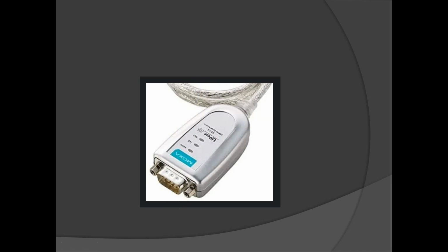terminal like Teraterm, or in the HDK you can open a console and you can frame a message. Okay, you can type a message, any words you can type. So internally, that message will be converted into UART frame format, and it will be given through these pins. Okay, there will be TX pin, RX pin, TX plus, TX minus, RX plus, RX minus. So what you can do is, you can connect the TX to RX, and basically you are loop backing.